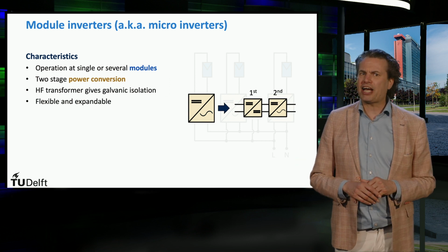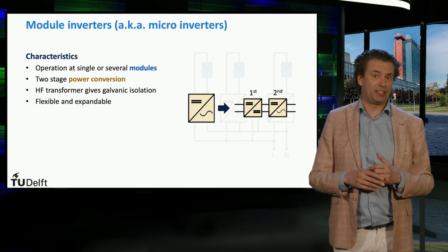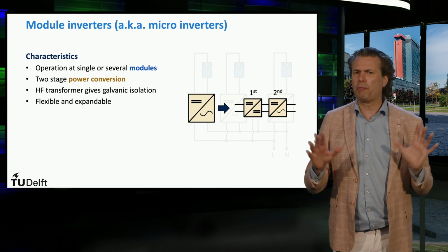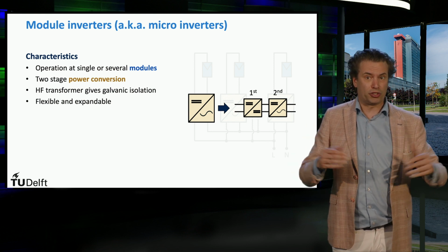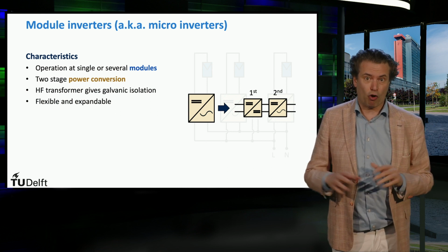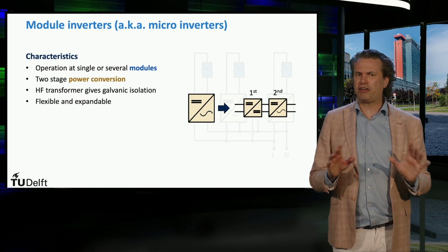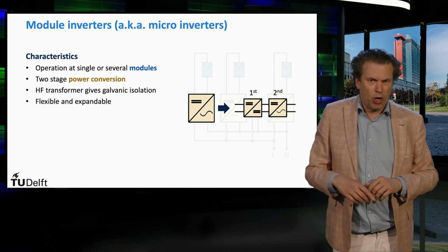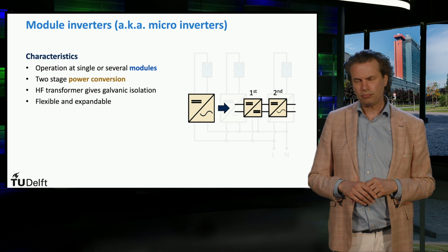The output voltage has to be compatible with the grid to which they are connected by means of an AC bus. In order to avoid phase imbalance, all the microinverters are connected together with special additional units, depending on the brand, which control the output signals of each inverter. As I mentioned, microinverters are very small, and this is because inside they have a high frequency transformer, which is cheaper and smaller compared to the main transformer.